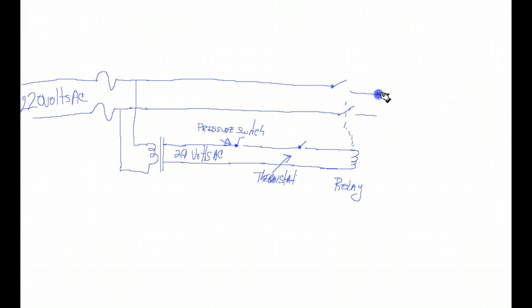There's one additional safety device located in here. And this is another switch, a thermal overload switch, a thermal switch. And this guy is located on the compressor, in contact with the compressor. So the voltage proceeds down through this thermal overload switch to the actual compressor.